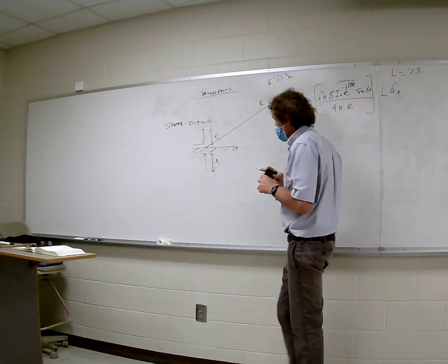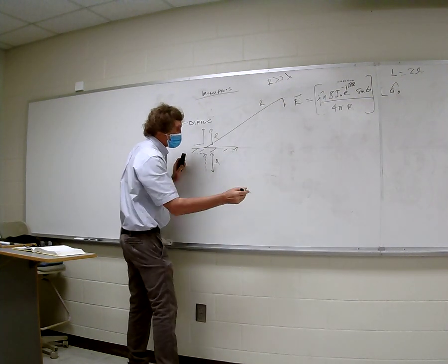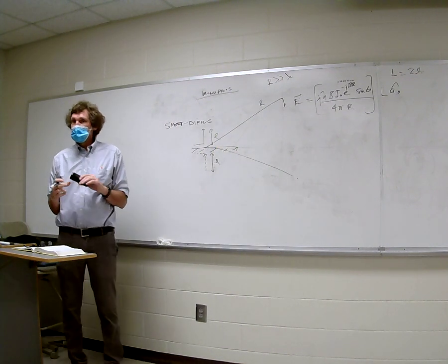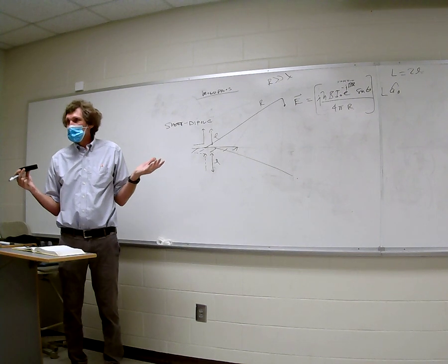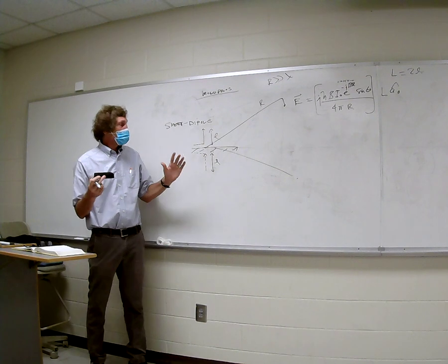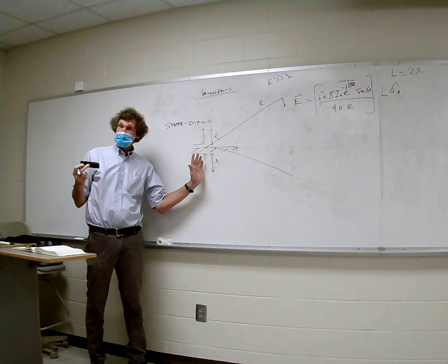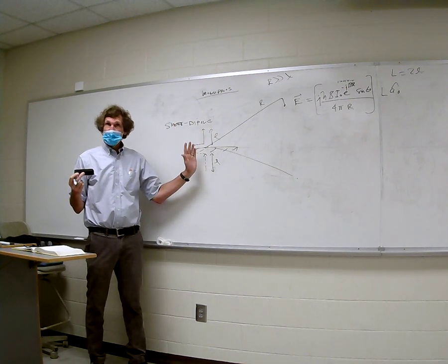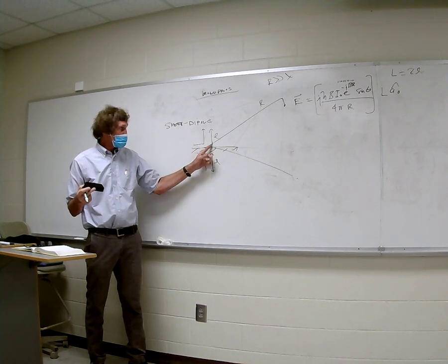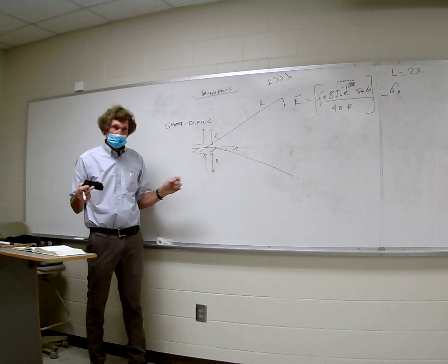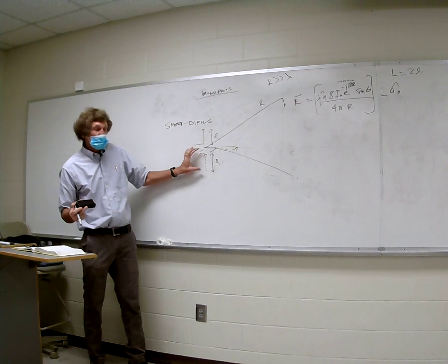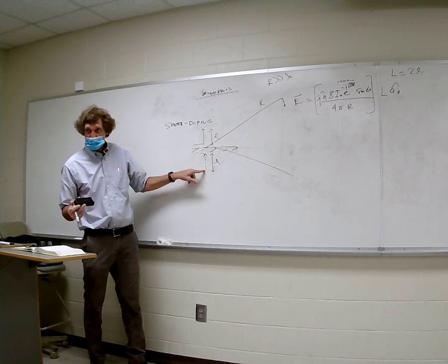Now, something else about this. Is there an electric field out here below the surface plane? No, there is none. One logical way of thinking about this: if I'm radiating a certain amount of power with an actual dipole, then the monopole would be the adjusted length. If this was a quarter wavelength, with its image it would actually be a half wavelength dipole, wouldn't it, class?